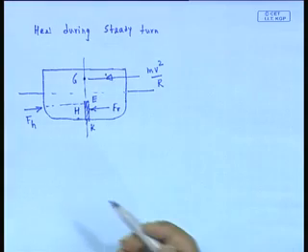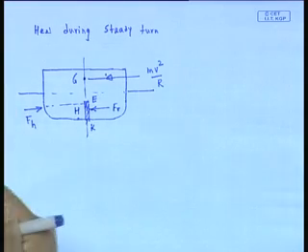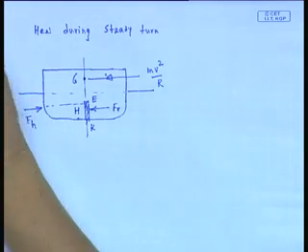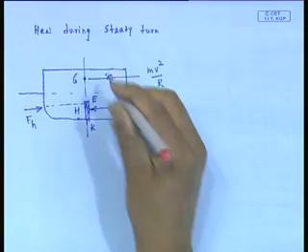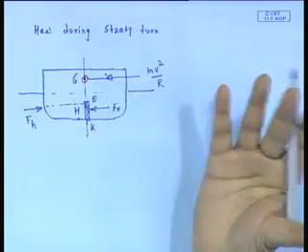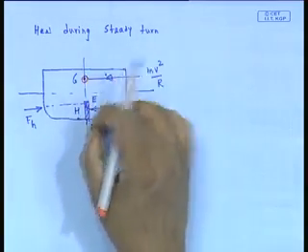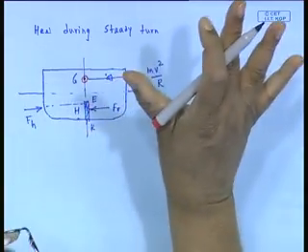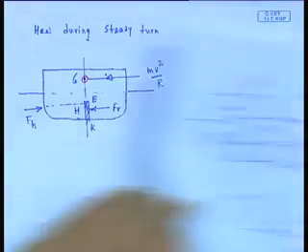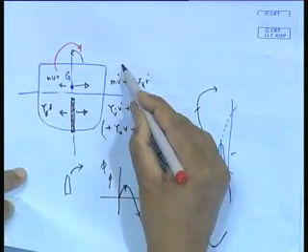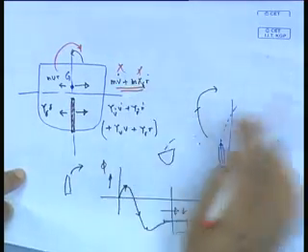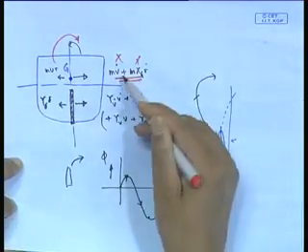What we are drawing here is something like this. Maybe I should have explained earlier: this is my center of gravity. We will of course take the moment about that, so we don't care so much, but this is all during a steady turn. Remember that the dotted part which I drew earlier is not there. These forces are not there, because we are on a steady turn. There is no V dot nor R dot.